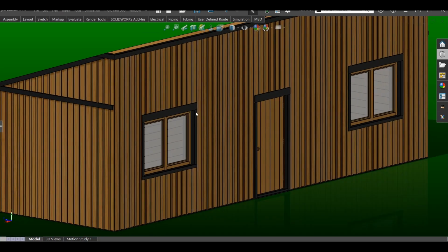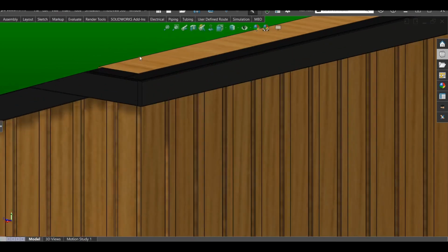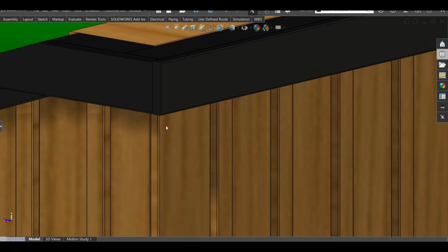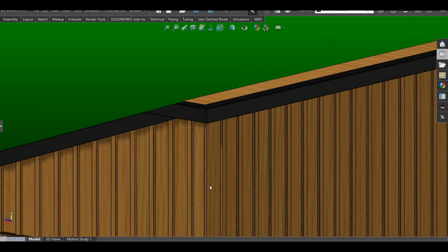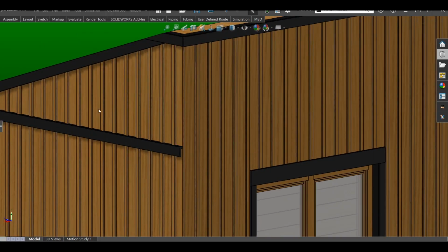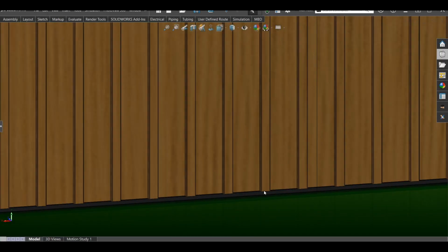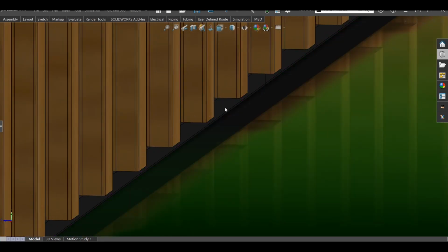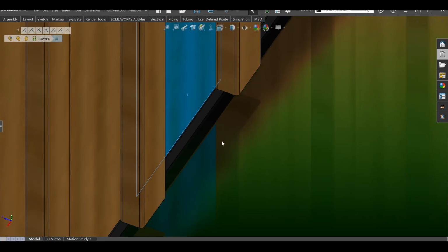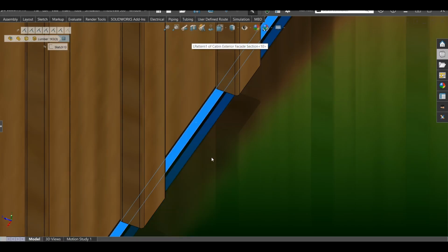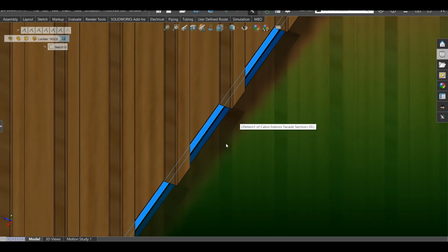But for now, I did a little bit of trim, by the way, real quick. You get these 1x4, 1x4. I want to put a corner here also. It looks like this, but I want to put a black corner. And I'm going to do a little cut there. It's still not finished. It'll be a black corner that goes from here to here, and I made sure also that this board is flush with this, so again when the rainwater goes in, it falls in the sheet metal flashing that I showed you earlier.